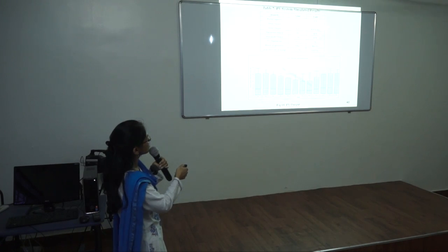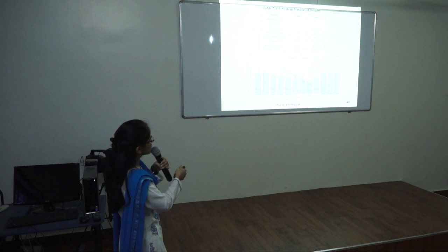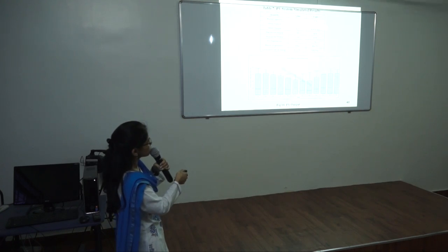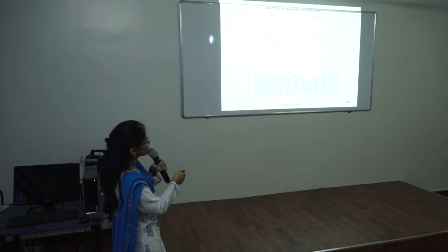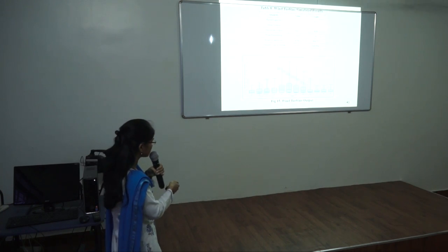The mean output is about 38.1 kilowatt with a rated capacity of 225 kilowatt and maximum output is 193 kilowatt peak. The levelized cost of energy only for the solar system is about $0.0175 per kilowatt hour.